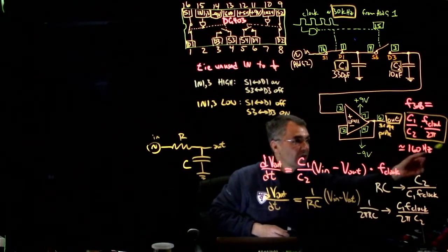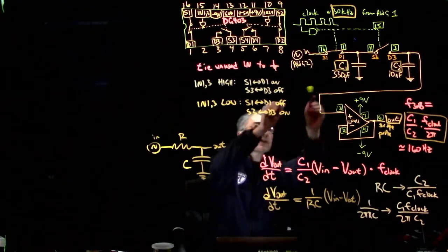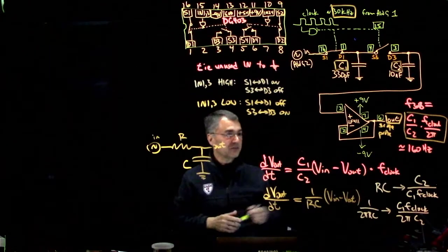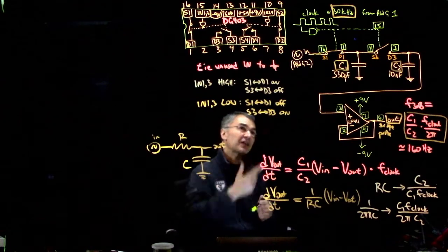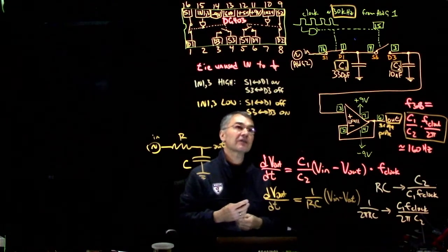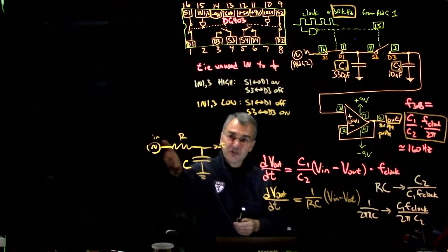And yeah, I actually got this to work on the first try. I wrote down Tom's expression, and I said, well, okay, let's reason through what this does every clock tick, and let's write down what the RC integrator does. And I was a little surprised, actually, that it worked on the first try. Anyway, so that's what it's doing. This is actually a neat way of making a low-pass filter. It's the same as the RC integrator, the RC low-pass filter.